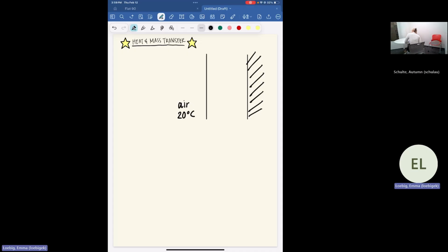Well, let's first tell ourselves that we have a uniform cross-sectional area. We are going to denote that using the variable A for area. Over here, we're going to mark this as position x is equal to 0, while over here, we're going to mark this as the position x is equal to L. Now, as you can see, the direction of positive increasing x values goes from left to right. This is going to be important later when we are worried about our consistency in our signage.